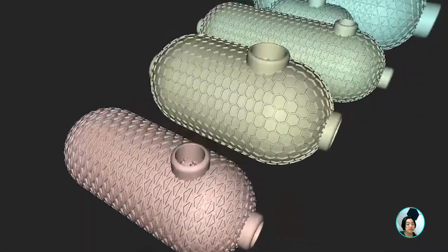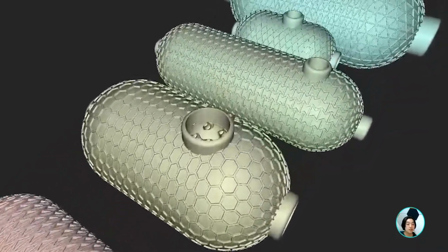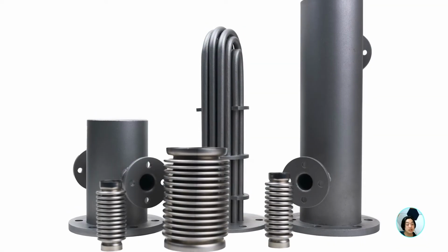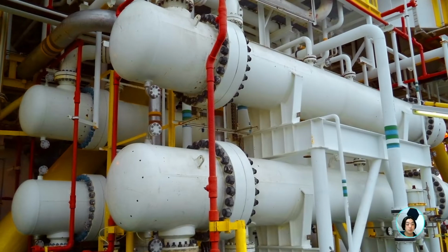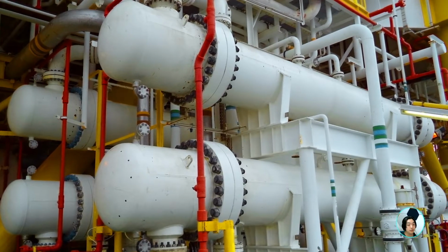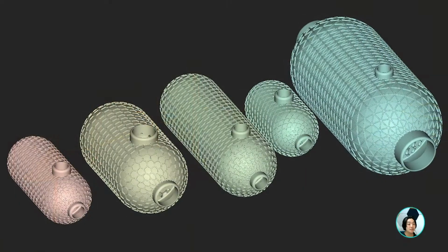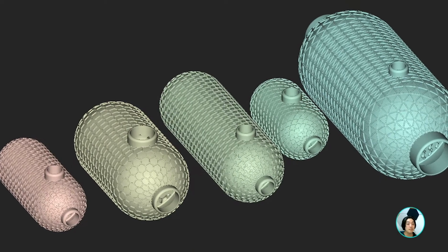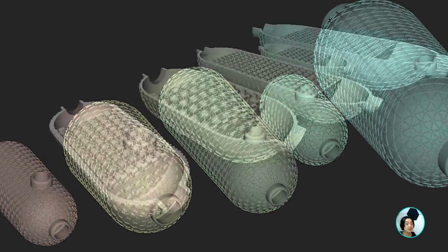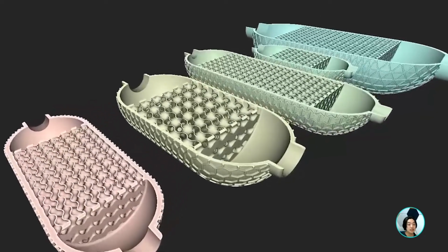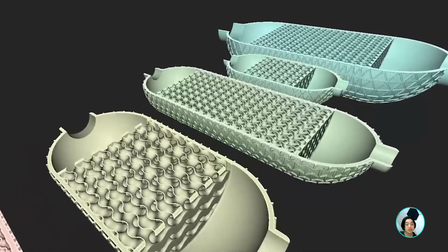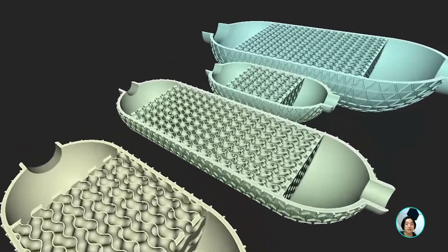There are many benefits of additive manufactured heat exchangers over their traditional counterparts. Standard shell and tube heat exchangers have many components. They require more space and have a chance of the shell side fluid leaking into the tube side fluid or vice versa. In comparison, you can condense a multi-component assembly into one where it is less prone to failure. These performance and reliability benefits can counteract increased costs, especially for high-performance applications in aerospace, automotive, or energy production.